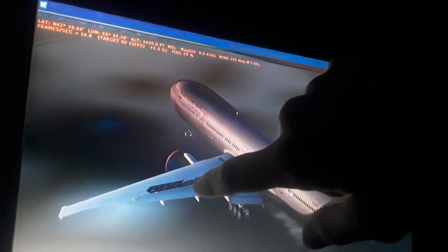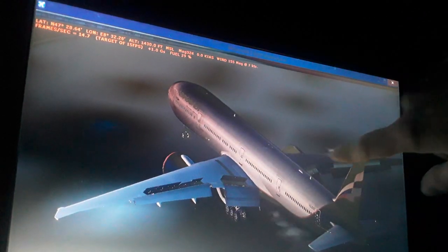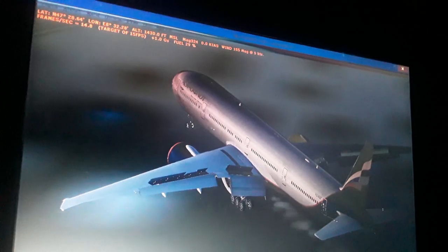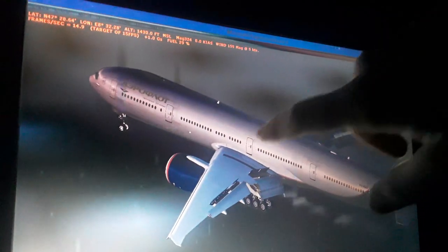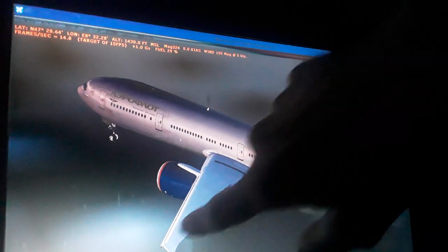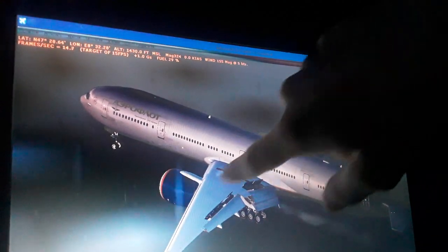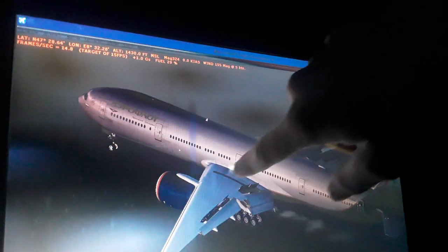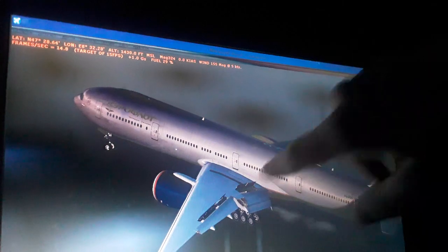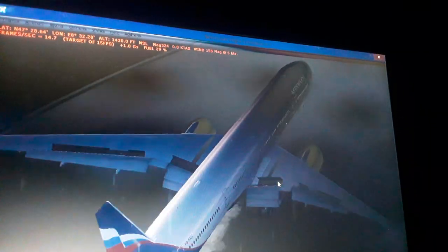So as I told you, here are the wings. This is the mean aerodynamic chord, about 35% of the chord of the wings. So we have also the position of the maximum aerodynamic lift pressure, and also the position where the stall of the airflow of the wings begins. There's also the position where the center of gravity of the airplane usually sits down here.